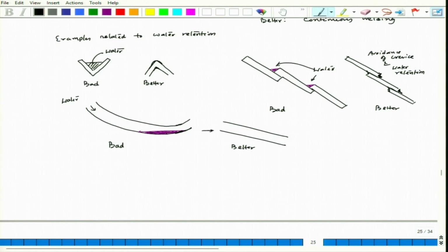Now there could be issues related to erosion corrosion. Erosion corrosion we have already talked about: using rounded corners or bends in a pipeline flowing water system, as well as a smooth pipe inner surface. If there are humps or a kind of dent, those dent as well as hump portions can lead to turbulence and can cause an extra bit of erosion corrosion.